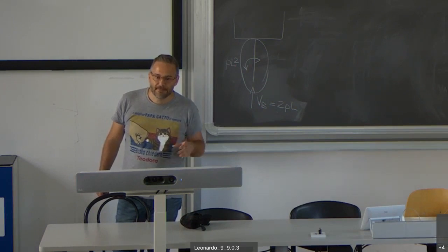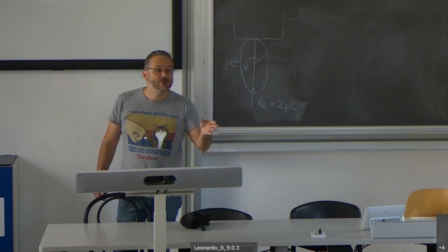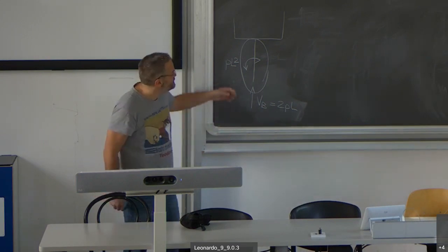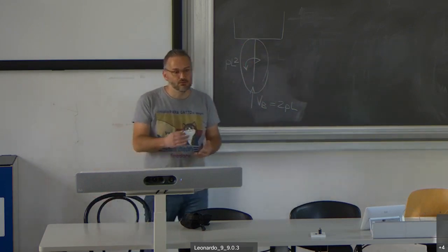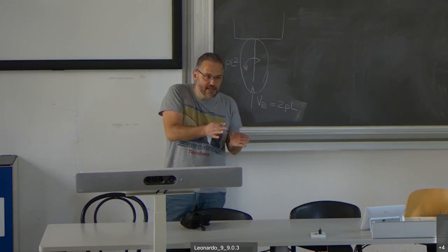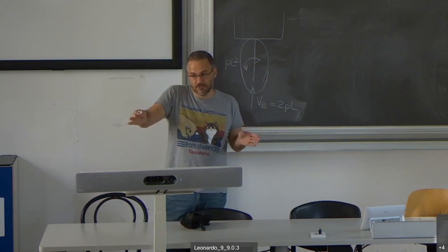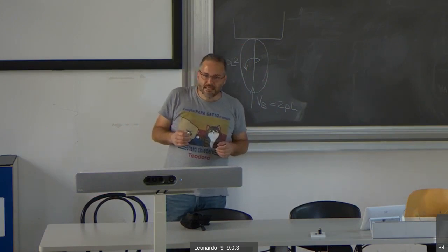More specifically, when you have concentrated moments, when you have concentrated forces in the middle of members, of straight members, it's always wise to consider what happens before the concentrated force and after the concentrated force, okay? Otherwise, you mess it up. Are we going to split the beam into two? Yes.